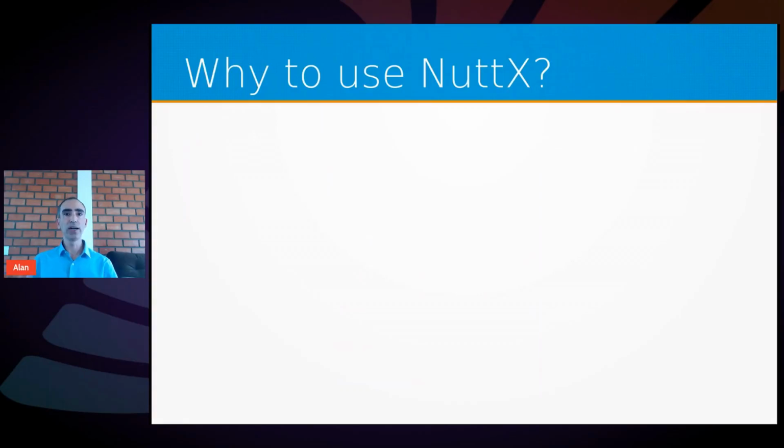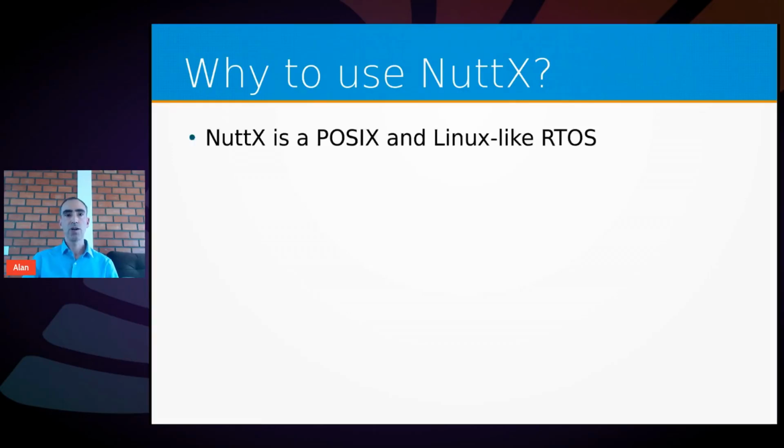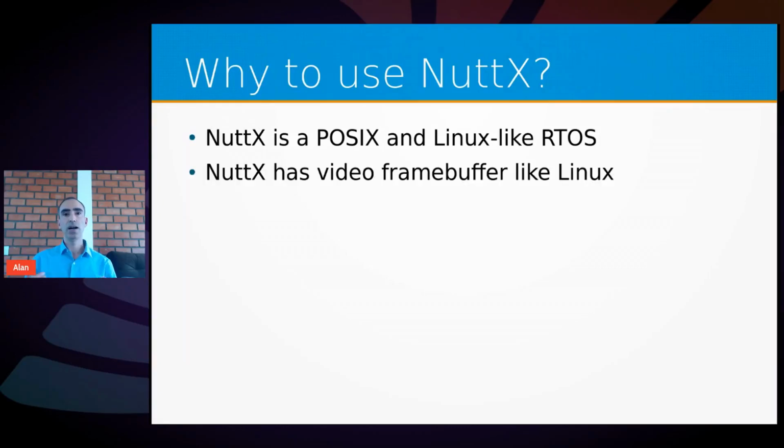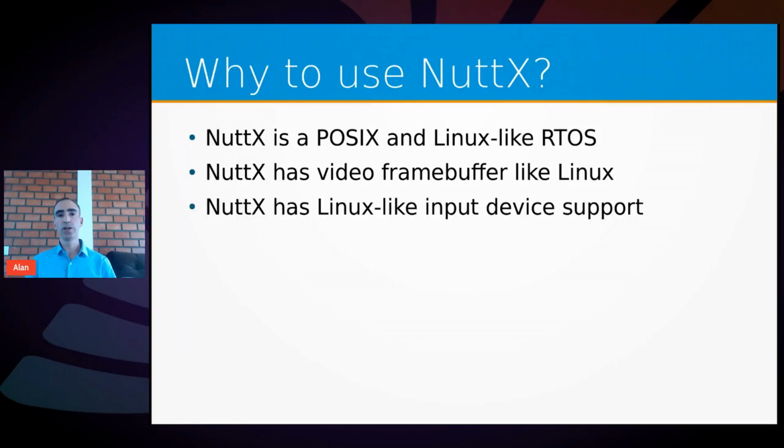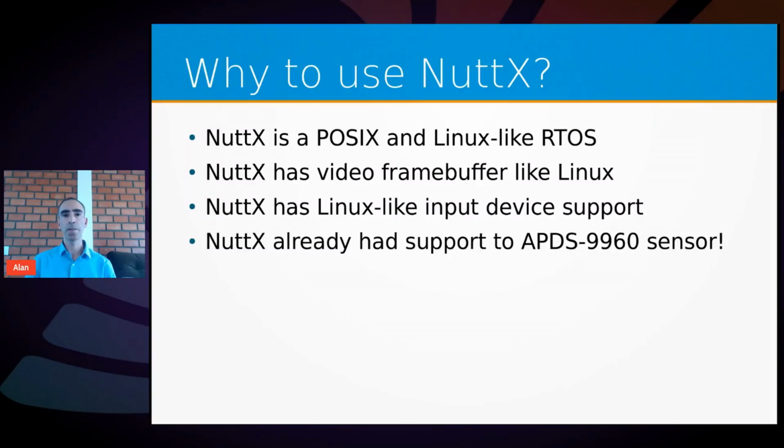So why use NuttX instead of Arduino or even some simple RTOS? First of all, NuttX is a POSIX and Linux-like RTOS. That means I can create the program using Linux. I can develop the logic and the interface and so on using Linux, and then I just recompile it for NuttX.